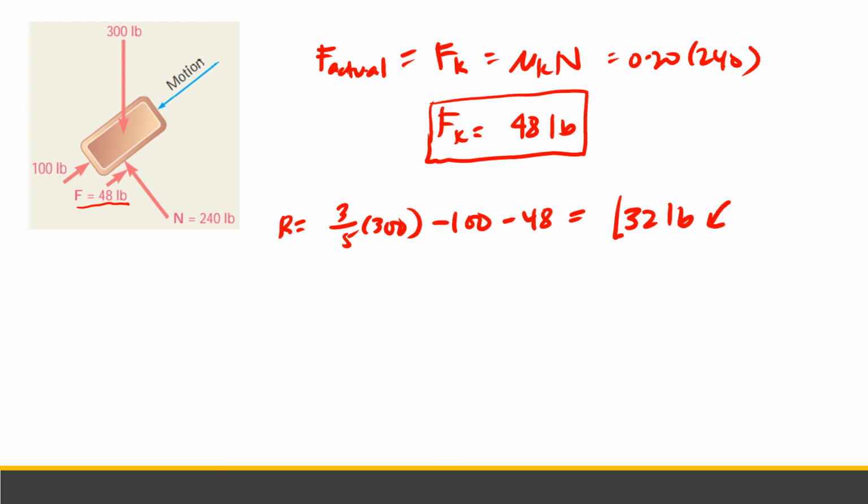This is the force while it is in motion. If we add an additional 32 pounds, you can totally block the motion. So to the 100 you add 32 to stop the motion. With 132, it becomes 0, meaning the block is static. Okay, so that is for example number 1.